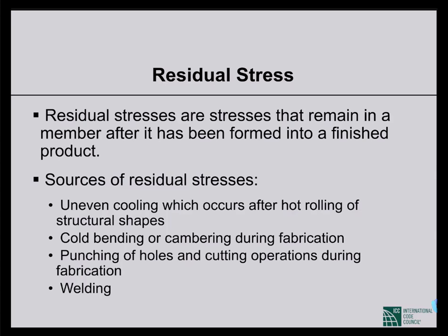When we punch a hole, just by the side of those holes, the material is no more elastic, because when you cut out material, just adjacent to the cutting surface, the material becomes inelastic. That means the level of strain is much higher than yield strain, so that causes stress inside the material. And as I said, welding is similar to uneven cooling.